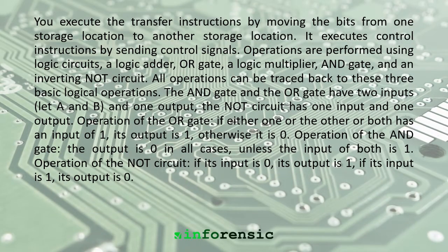It executes transfer instructions by moving the bits from one storage location to another. It executes control instructions by sending control signals. Operations are performed using logic circuits: a logic adder, the OR gate; a logic multiplier, the AND gate; and an inverting NOT circuit. All operations can be traced back to these three basic logical operations.